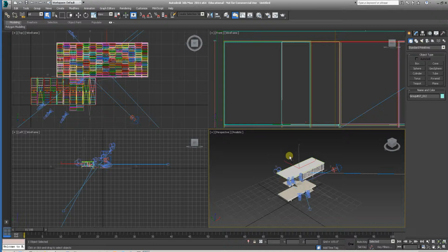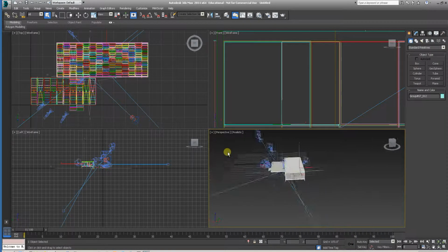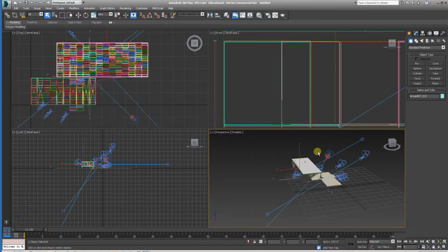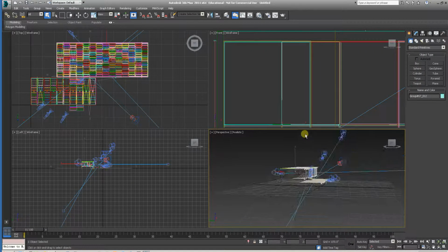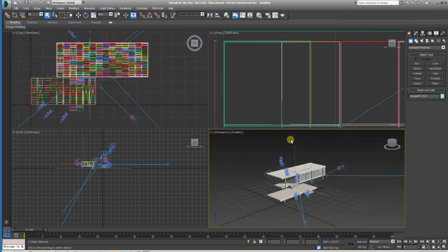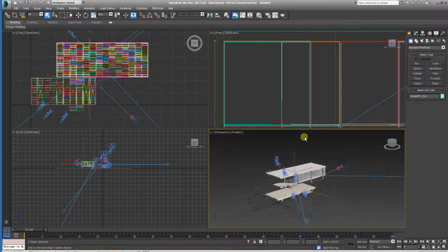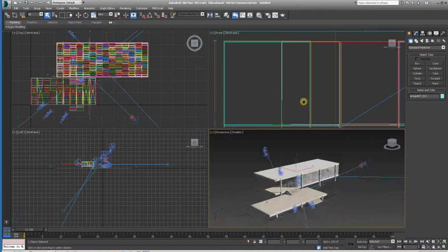If you hold the Alt key down in the perspective viewport and click the middle mouse button instead of panning, it will orbit the viewport for you. So that's the basic moves. You can combine the control with the Alt key for rotating with control to zoom in without using the scrolling the middle mouse button, and then let go of both to pan.